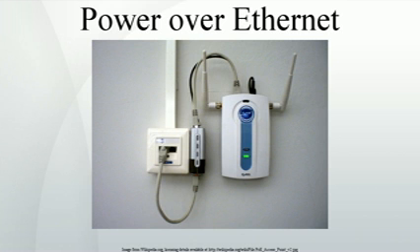There are competing data and power technologies. The Universal Serial Bus, USB, provides both data and power, but it is designed for short cables with a maximum length of 5 meters, 16 feet, and provides less than 2.5 W of non-isolated power. It is less expensive than PoE, and works well for low-power peripherals such as a computer mouse, a headset microphone or a serial port. Some peripherals, such as speakers, scanners and printers, need more power than USB can provide.